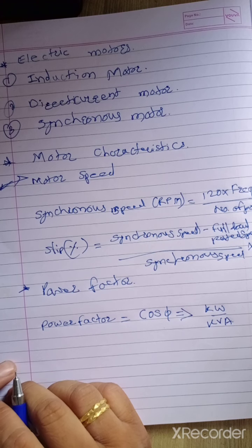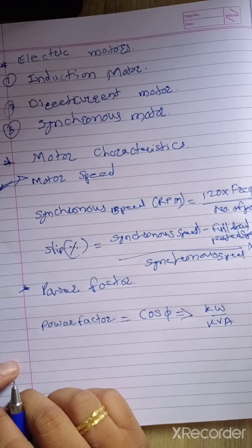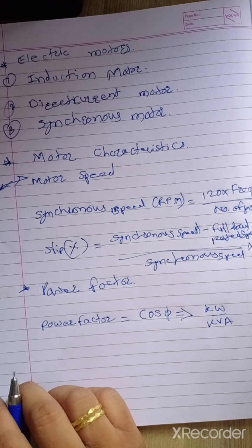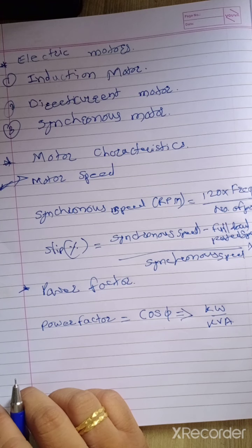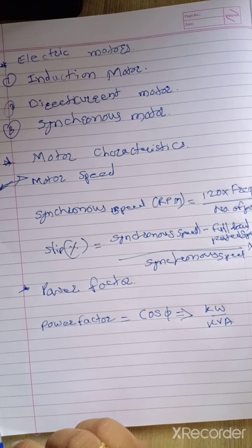As the load on the motor comes down, the magnitude of the active current reduces. However, there is no corresponding reduction in the magnetizing current, which is proportional to the supply voltage, with the result that the motor power factor reduces with reduction in applied load. Induction motors, especially those operating below their rated capacity, are the main reason for low power factor in the electric system.